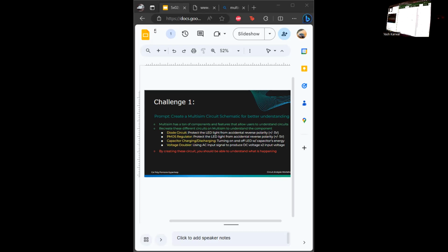You put a probe across the capacitor. That means I have to stop it. The fun thing about Multisim Live is that it has an on-screen oscilloscope, so you can actually see the time passing and what happens as the circuit runs. All right, are you ready? It's charging, it's discharging. Earlier, remember how it was only like 11 volts? But now it went to like 6 volts, right?